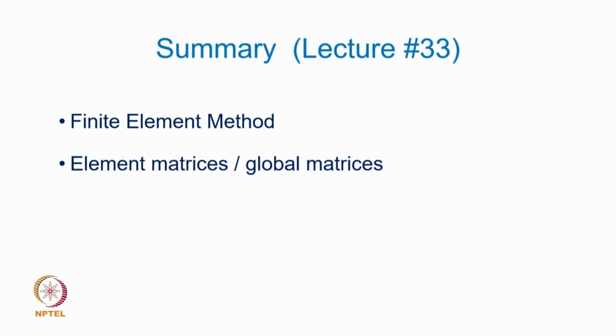The concept of element stiffness and mass matrices, and how the matrices get assembled to generate global stiffness and mass matrices, is what we have discussed in the lecture. And finally, you form the governing equations of motion in the matrix form, which you can then solve in a standard way for eigenvalues, eigenvectors, and also forced vibration response.